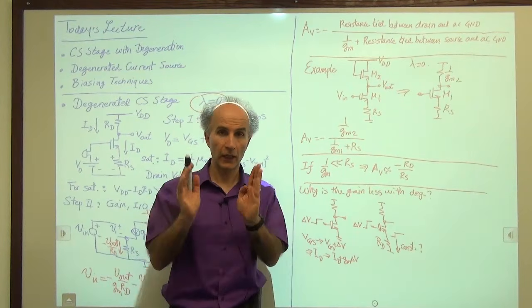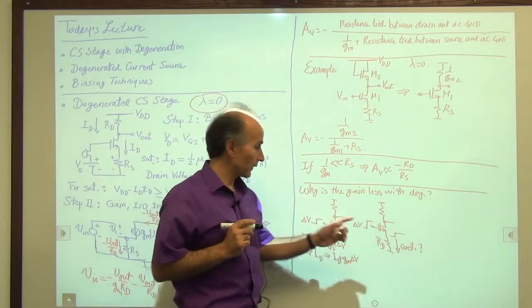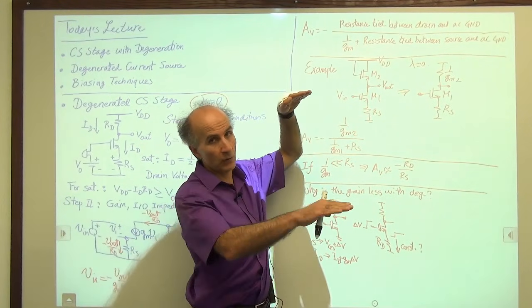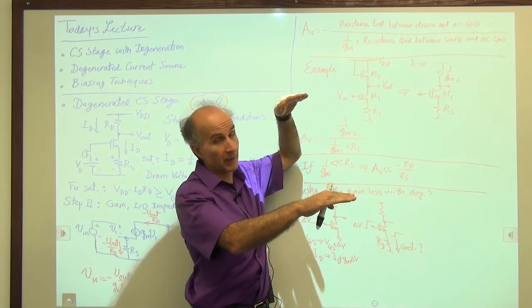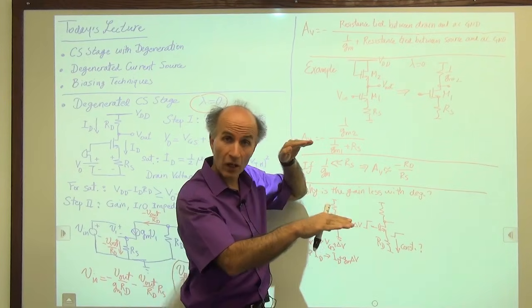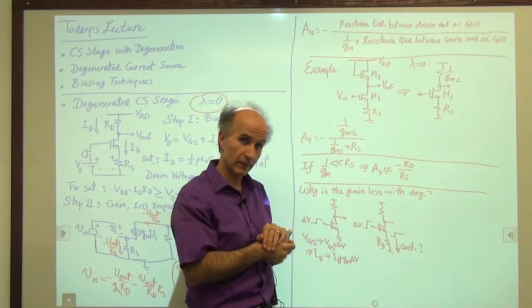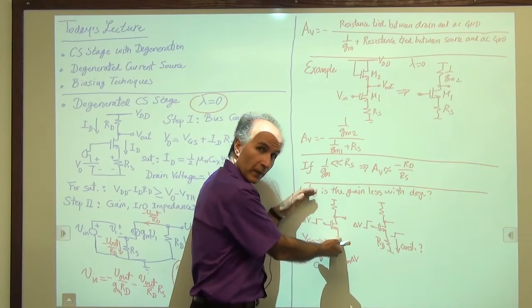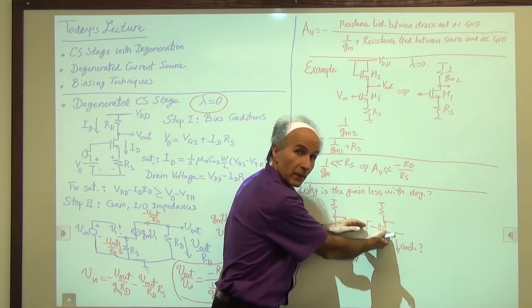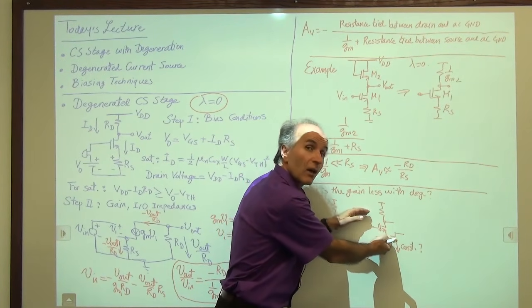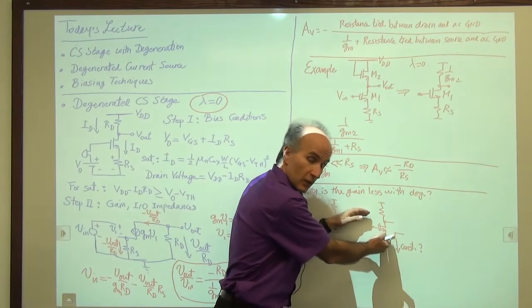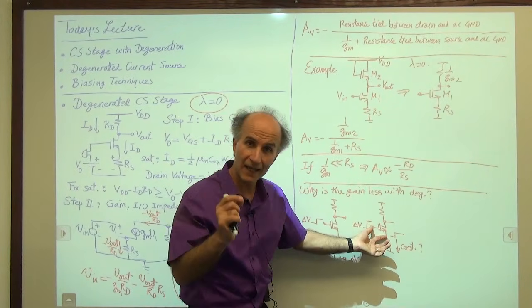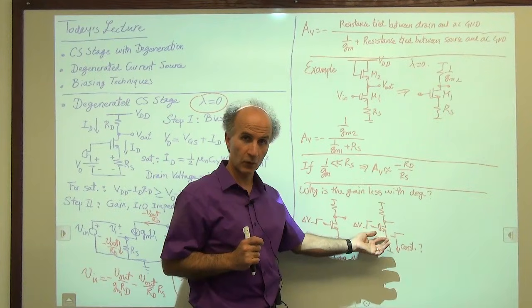All right, so here comes the interesting point. In this circuit, what we see is the gate voltage goes up. The source voltage goes up by some amount. That means that VGS does not increase by delta V. Here, VGS increased by exactly delta V because the source was fixed, the gate went up by delta V. But here, it did not. The gate went up by delta V, the source did not go up by delta V. The source was not constant, the source went up by some amount. So this VGS changes by less than delta V because the source keeps going up.